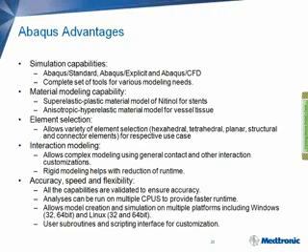General meshing and element selection allows for economic solutions without compromising accuracy. For example, we can model guide wires with beams, delivery tubes with cylindrical shells, and stent struts with solid elements to reduce runtime but still obtain accurate results. In some cases, axisymmetric elements can be used to model axisymmetric geometries and loading. In addition, connector elements which connect two nodes in the model help with modeling of mechanisms like hinges and sliders.